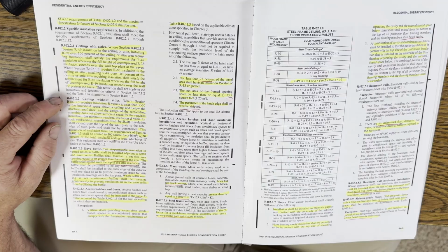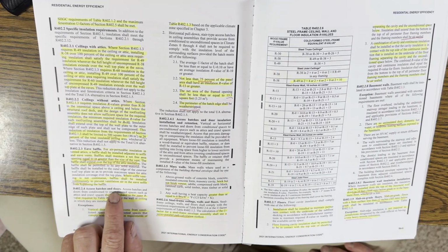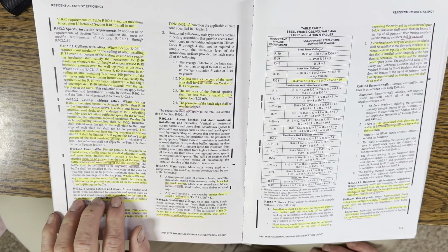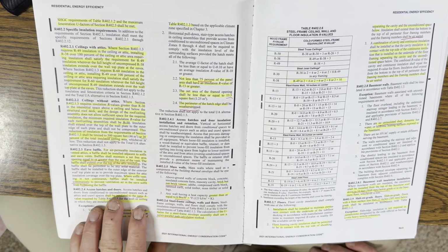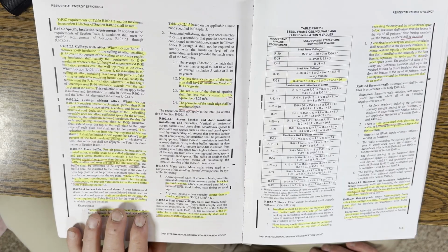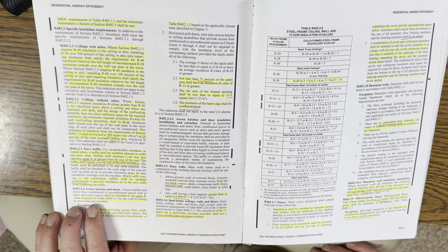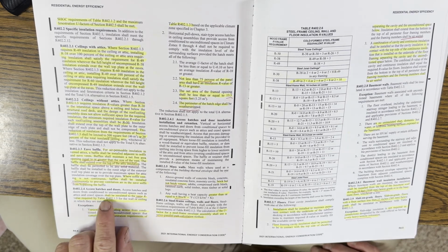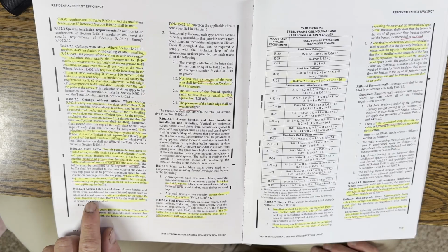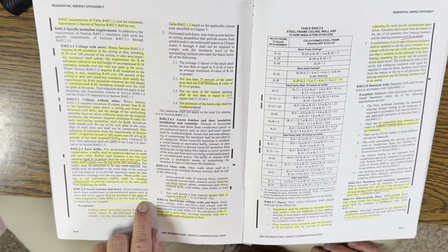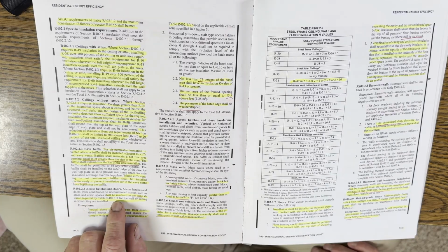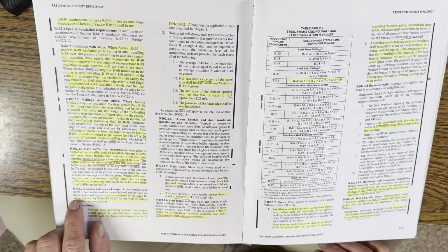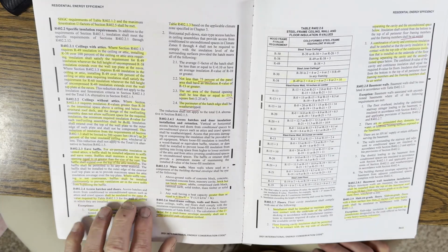Had a question on access hatches and doors. I think this was a Summit County, Colorado question, so climate zone 7, a door on a house like 9,000 feet high. What's the minimum R value? In this case, it says shall be insulated to the same R value required by table 402.1.3 for the wall or ceiling in which they are installed. It was an exterior door, even though it says access hatches and doors from conditioned to unconditioned spaces, such as attics and crawl spaces.